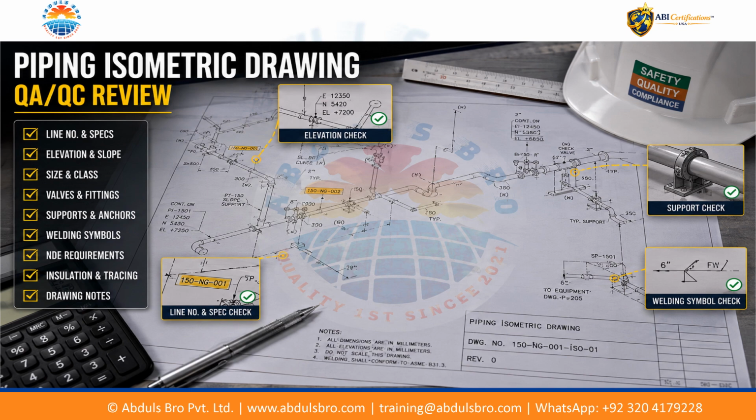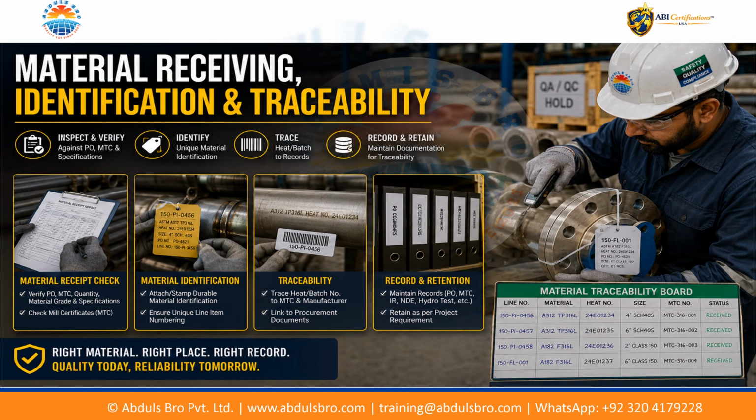Material receiving, identification and traceability. Piping quality begins with effective material control and traceability. Pipes, fittings, flanges, gaskets, and valves are verified against applicable material specifications, grade, size, class, and approved certification. Required markings and identification must remain traceable throughout construction. Materials are also examined for damage and properly preserved during storage and handling. Particular attention is given to end protection, coated or lined components, and stainless steel segregation, ensuring only conforming materials are released for fabrication and installation.